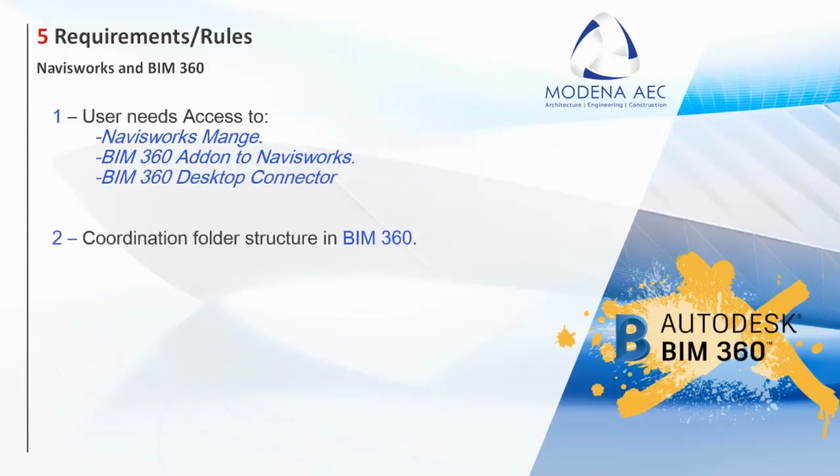In terms of rule number 2, you need a coordination folder structure in BIM 360 for your Navisworks file. The reason for this is we would like to keep the federated Navisworks model away from the designing models of Revit, AutoCAD, Inventor. If you can isolate them apart, then it's much easier for you to run coordination. Rule number 3, you need access to all the models. And the access is actually very particular. You need view and download access.